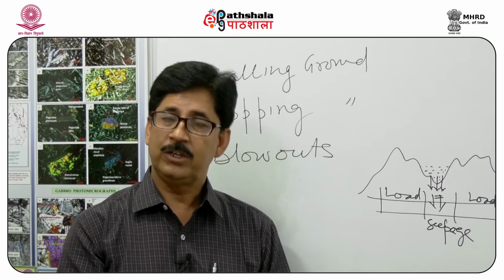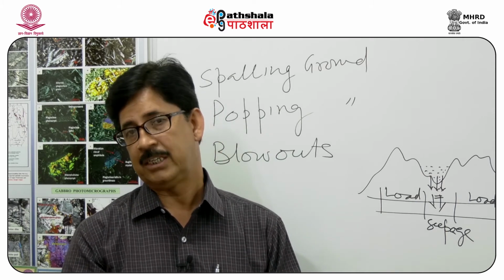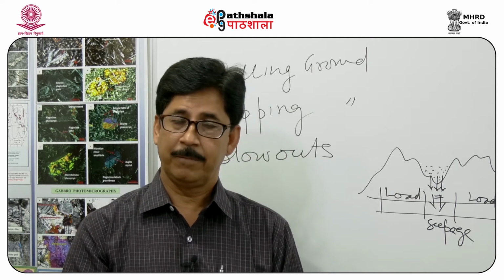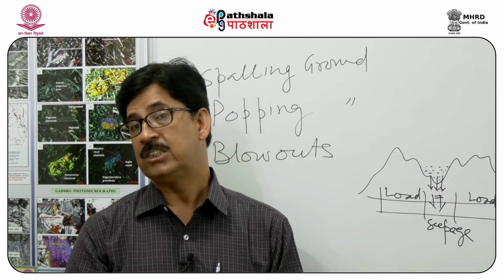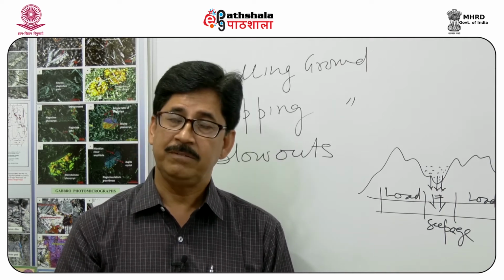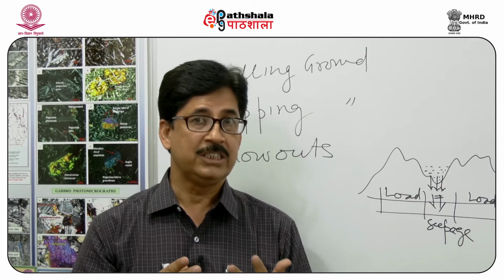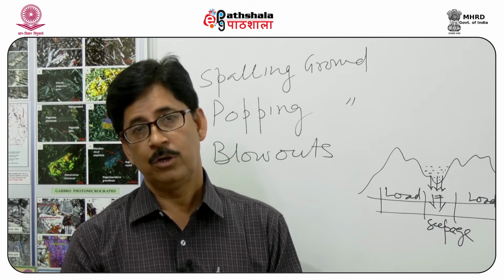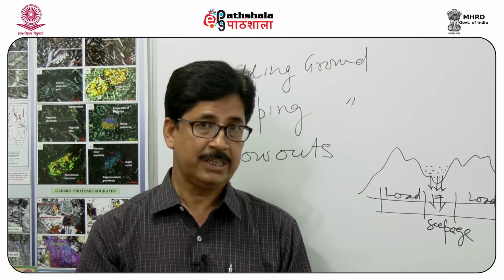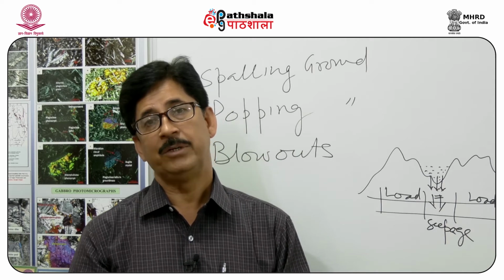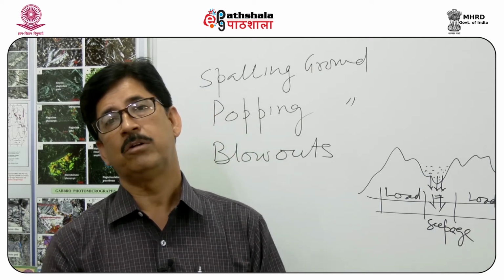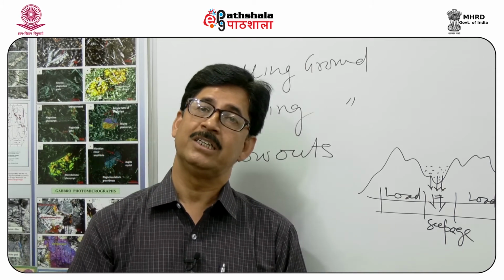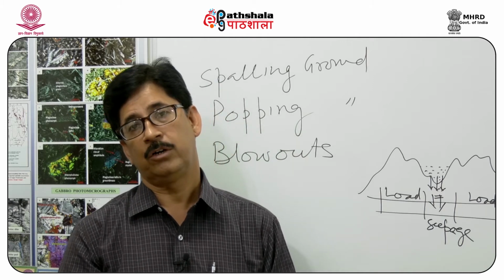But with softer rocks, we will have a lot of problems. If it is sedimentary rock, for example, then we may have a chance of a lot of groundwater. But if you are working in igneous rocks, the rocks are massive. There, the rocks are very strong. The rate of advancement of the tunnel may be slow, but your tunnel will be much safer. Similarly, in metamorphic rock, if it is non-foliated metamorphic rock, then the tunnel will be much safer as compared to tunnels in foliated metamorphic rocks.